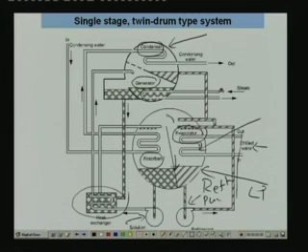And this water vapor comes to the absorber side, because this side pressure will be slightly higher. This water vapor comes in contact with the absorbent liquid in spray form. The absorbent liquid is also sprayed here. So water vapor and absorbent liquid are mixed here, and they drop onto this cooling water coil. The mass transfer and heat transfer takes place on the cooling water coil. Heat is generated, and this heat is picked up by the cooling water, which enters like this, flows through this coil and takes the heat of absorption. Finally what you have here is a weak solution of water and lithium bromide.